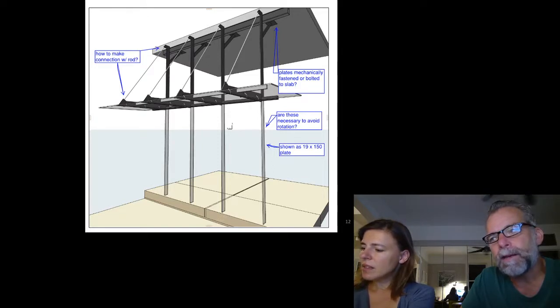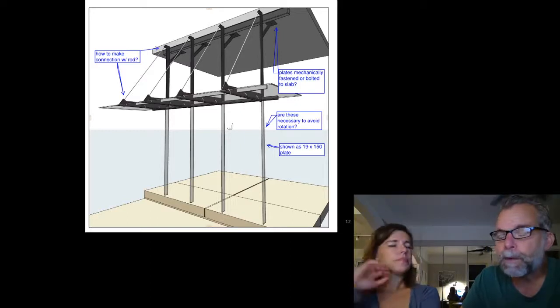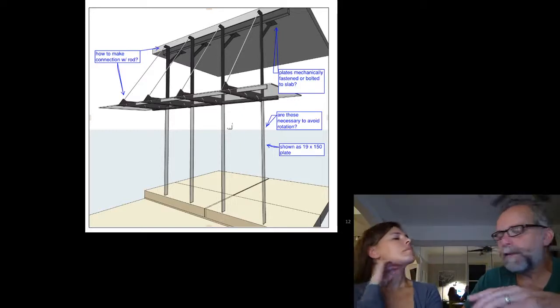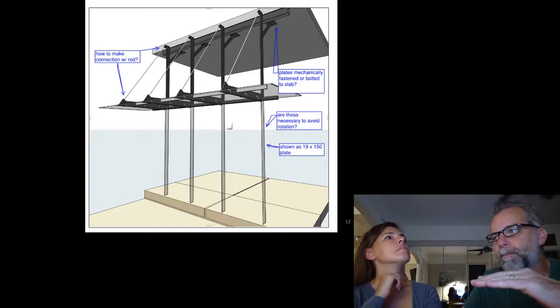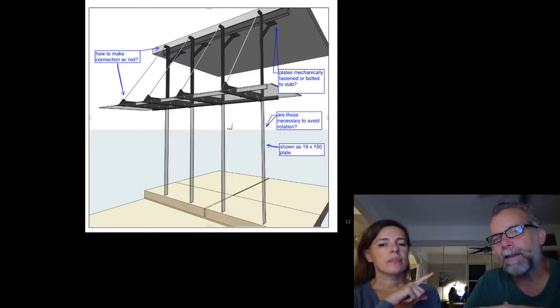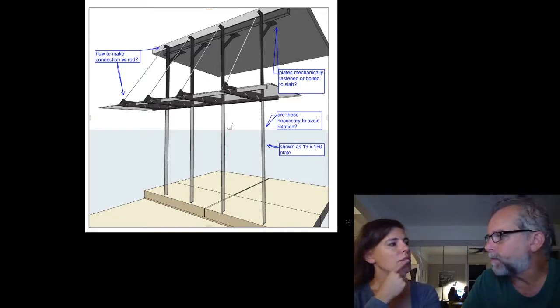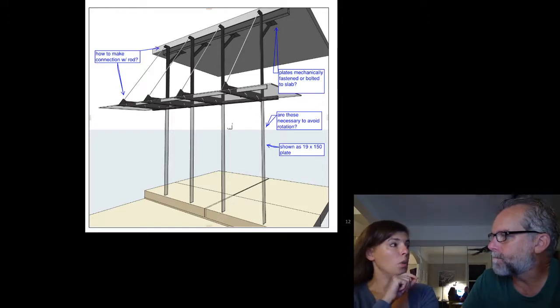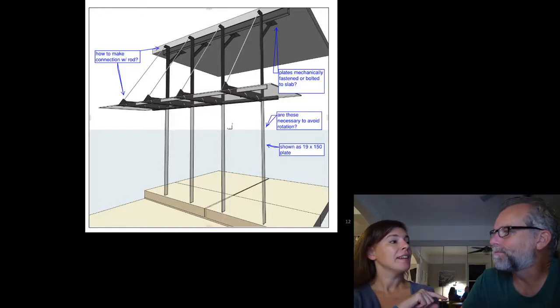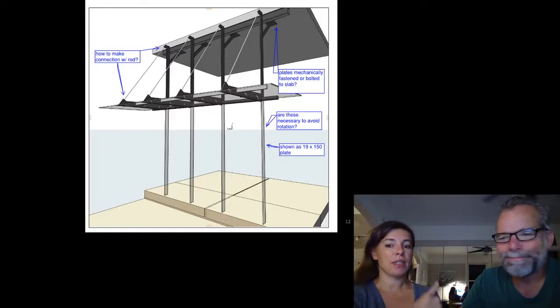a possibility. Anytime you're doing a green roof, I mean, we do tons of green roofs. A green roof generally is heavy enough to resist the wind uplift. So you've got an automatically ballasted system, which makes these tension rods unnecessary. There are some clauses now in the Toronto wind uplift report and green roof report that you have to assume some amount of your green roof is being blown away by the same wind you're using it to resist.